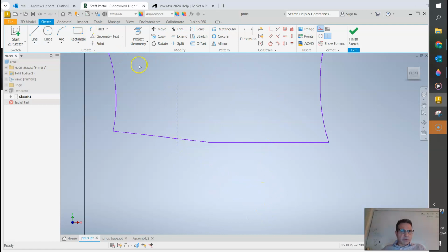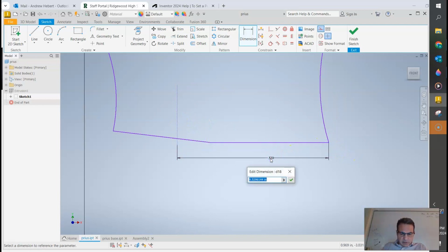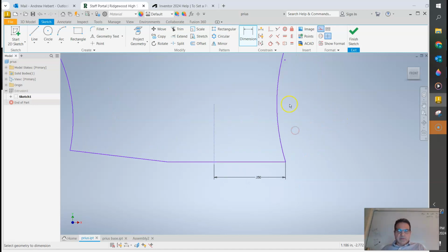Let me show you what I'm doing. So first of all, I want to remove a 1/4 inch. So the distance of this cut is going to be 0.25. Okay. The height of the cut is the same as the thickness of the wood, 0.135. All right, so that's the location of the cut.